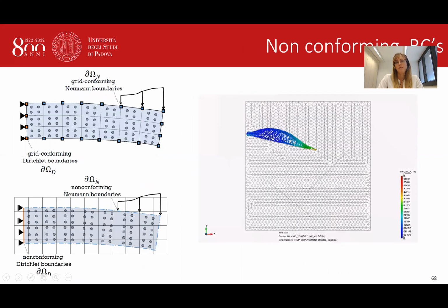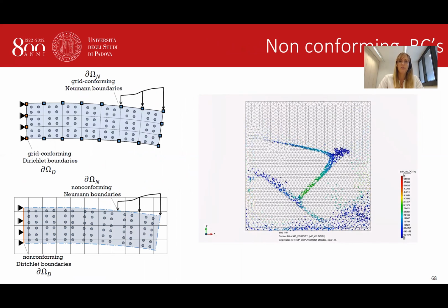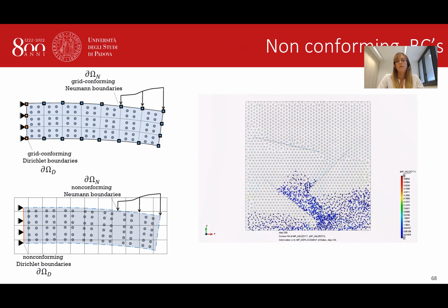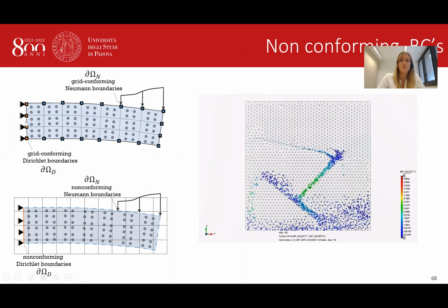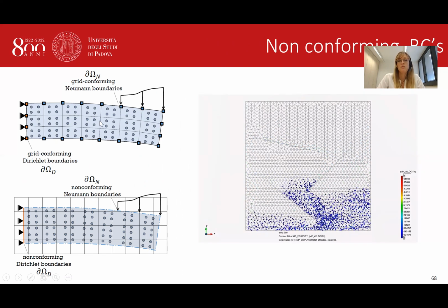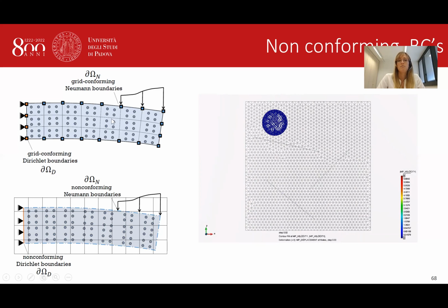The problem is that in many cases, if you have a surface boundary condition, not a volumetric one, in which case it's easier, or if you have moving boundaries, then things get much more complicated, because often you don't have a mesh on which to impose your boundary condition. Or, for example, consider this undeformed beam at the beginning, and consider it a very, very flexible beam. Then it will be subjected to large deformations. And if you are imposing a force here, this force should follow your material points on the boundary, while the mesh behind will stay in its original position. So something like this will happen. How can you do that if you're imposing your boundary condition on the nodes? Well, you cannot impose them on the nodes. You have to find some way of imposing your boundary condition on the material points, and then transferring it to the nodes with the least error possible.